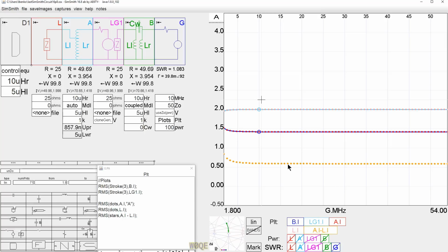And lo and behold, it's a much lower current. This means that we're capable of using a smaller wire gauge if we wish to for 70% of the turns. Remember that this transformer is set up to be an impedance ratio of 2 to 1, which means that the turns ratio is the square root of that value. So it's 0.707. So this is 70% of the turns.